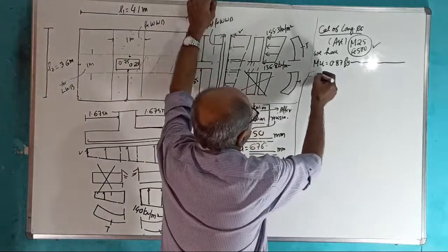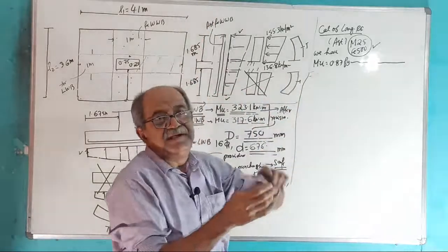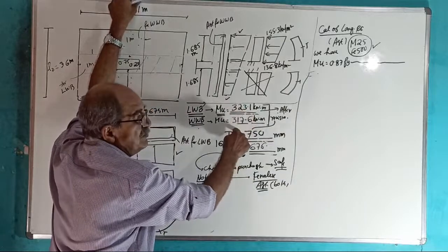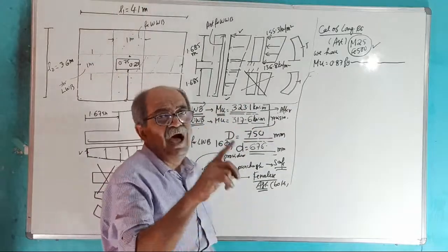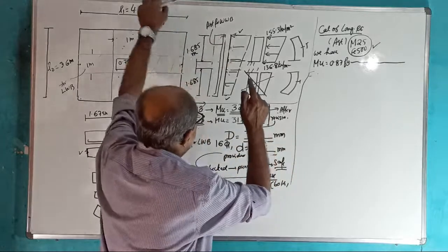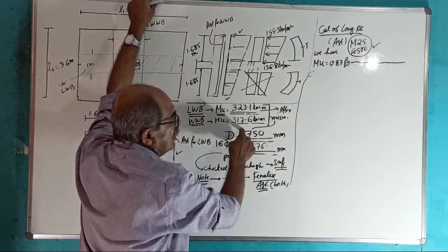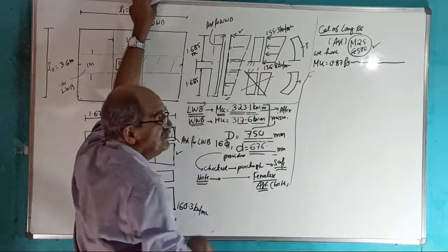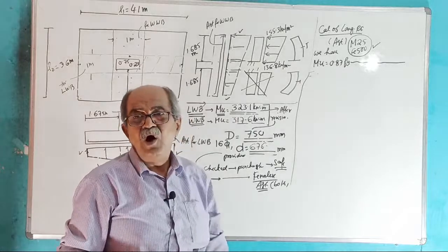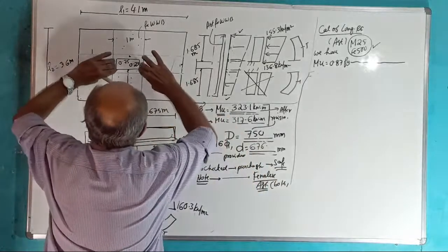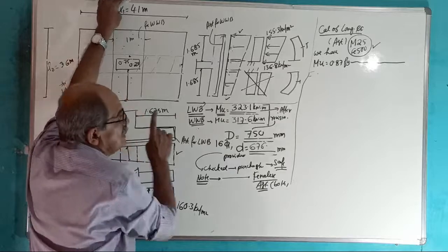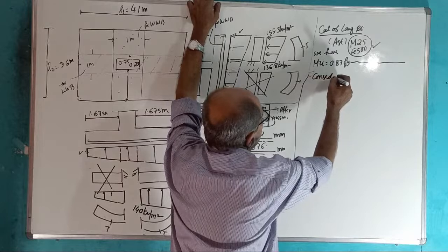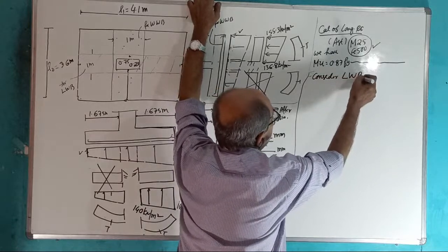Now, when you decided the depth of slab, you considered whichever is higher BM. Depth you fix based on higher MU. But reinforcement you have to give separately for both. Actually, both are almost the same. Tell me why both are almost the same? Because we maintained the same projection on both sides. This I told you. Anyway, start. First consider lengthwise bending. Start.